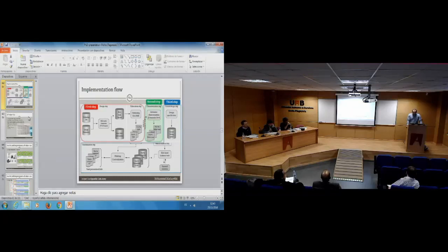But if there is a technology providing something like 80 or 90% yield, one of the solutions that I already mentioned is that we can start metallizing, customizing several foils to the same functionality and stop when the first one is working. It means stopping when we are using the working transistors actually by chance on the substrate in order to build that circuit.